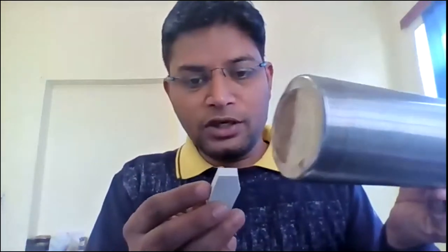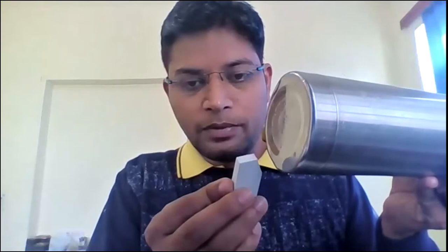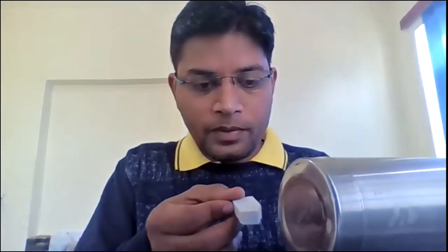When you go for a machining operation, now when you give the depth of cut, you will hold like this, give the depth of cut and move in this direction. Now please look here, initially this was the surface which was coming in contact with the workpiece material, right? Now you have to make the edge, you have cut the surface at some inclination angle. So now this tool looks like that.